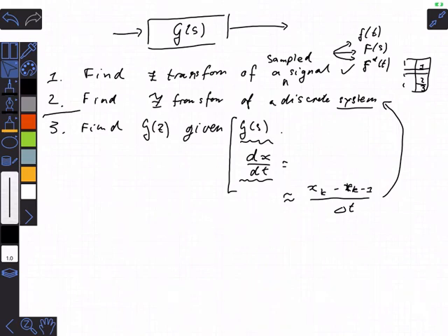They'll be longer to calculate. They'll have a greater latency. They tend to be more accurate on smooth signals and so on. So there's a couple of different discretizations that we can do. The only one that I want you to know by heart is the backward difference approximation. But the most important thing that I want you to know about these things is that these are very different things.